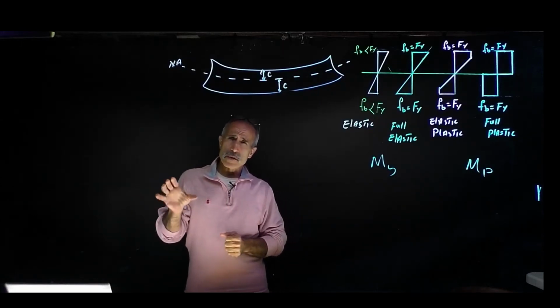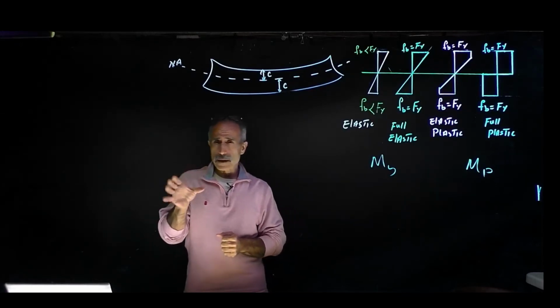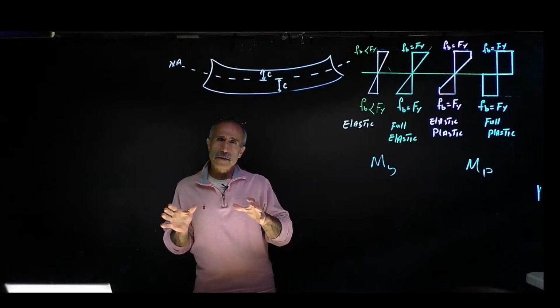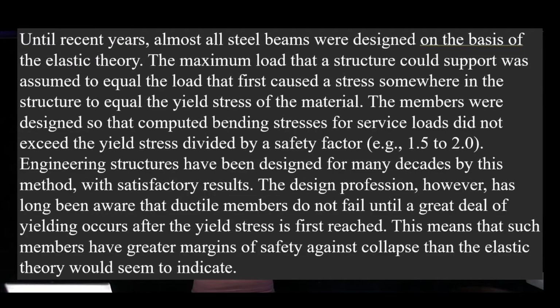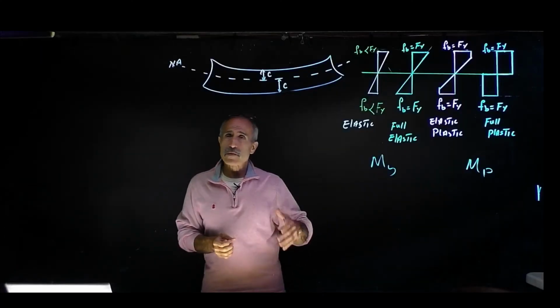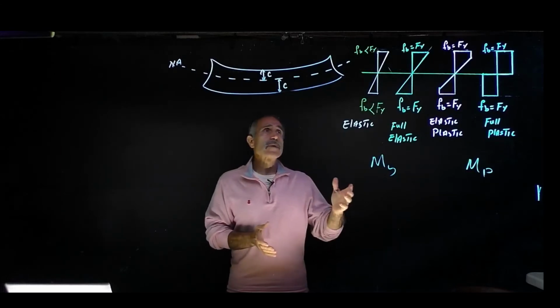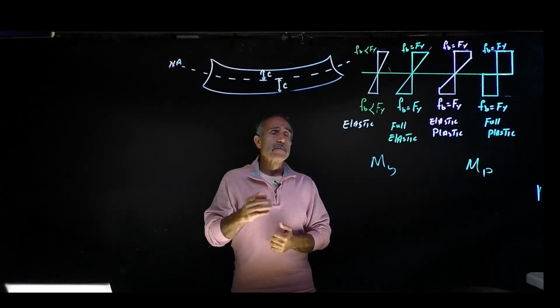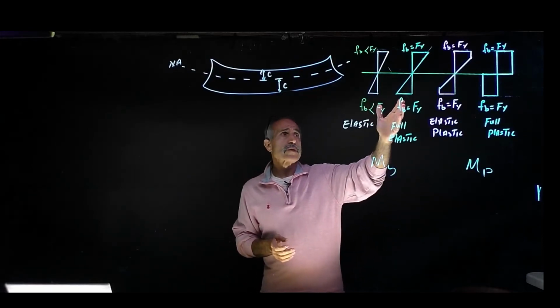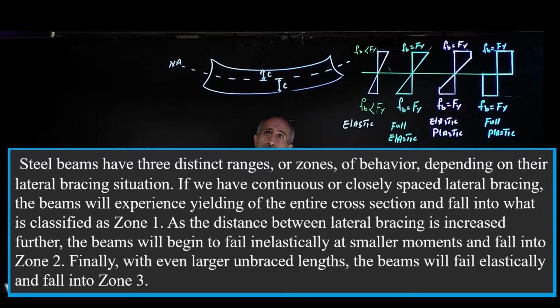In this lecture, we're going to talk about steel beam design based on bending moment. When you look at steel, because steel is so much different than wood, timber and concrete, depending on how the beam is situated and how it's laterally supported, the steel beam design could fall in a different zone. For example, when we did timber and concrete, we tried to make sure that we stay below the yield stress. But in steel, we can go beyond yield stress, to plastic design.